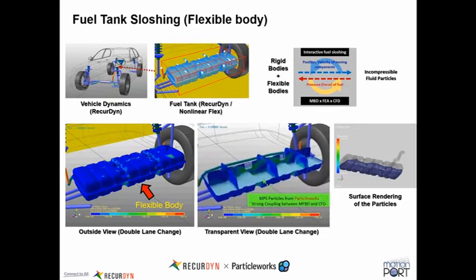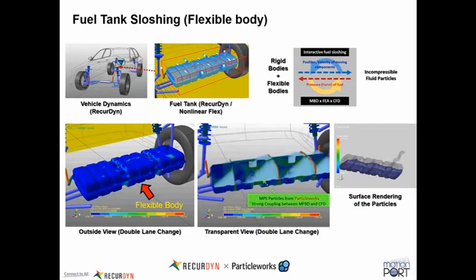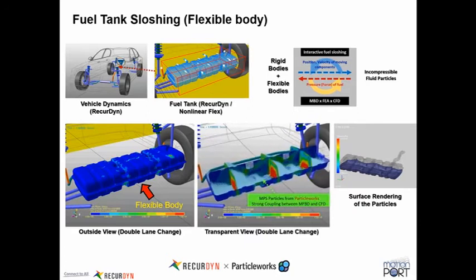I've run things that are somewhat similar to that in a few hours. It's highly dependent upon the number of particles and how many elements are in your mesh as well. If you're not careful, you can get things that will run for several days. So you do want to be a little bit careful about how many elements you have in it, but I'd say something like this could probably be done in a few hours.